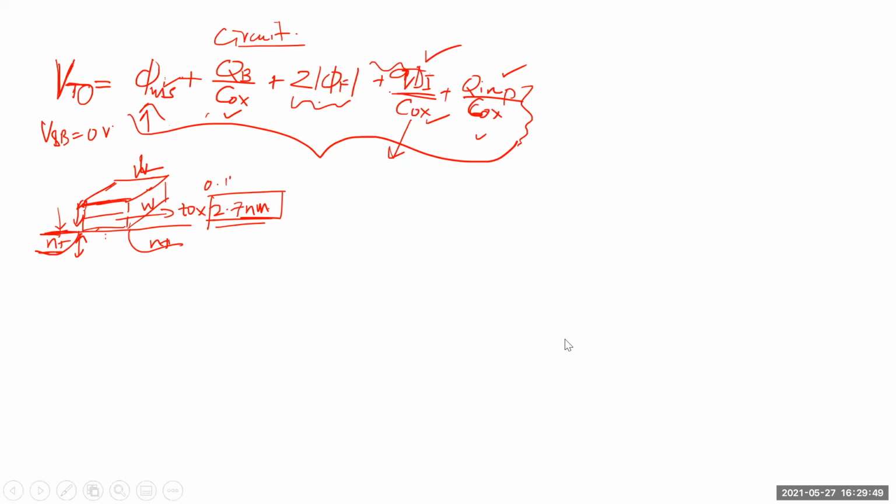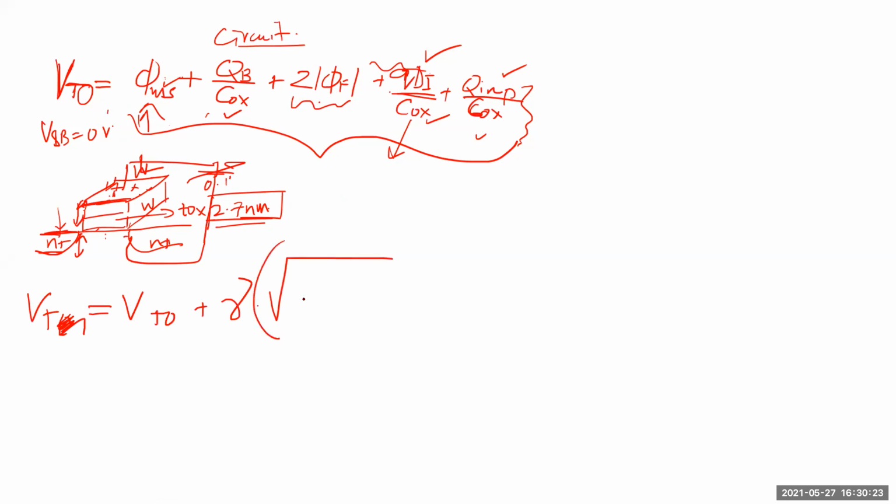So sir, we can control the charge by putting different potential. Yeah, of course you can do that. You can put a voltage here, change the voltage, and the charge will be different here. But for the VT, there is no dependence on W, L and charge voltage, right? VT is these parameters here. And if I take the complete equation, let's say VTN, then it is VT0 plus gamma times root of 2 phi f plus VSB minus root of 2 phi f, right?